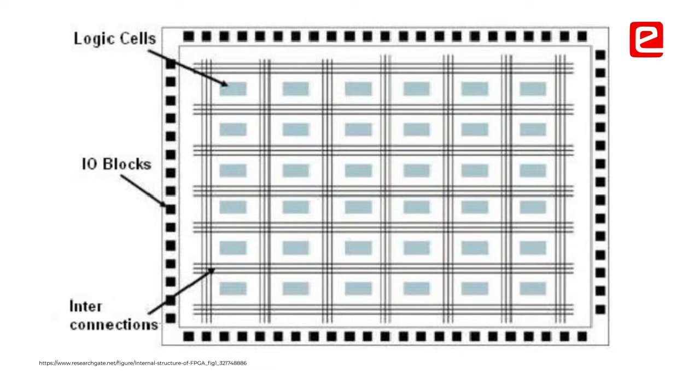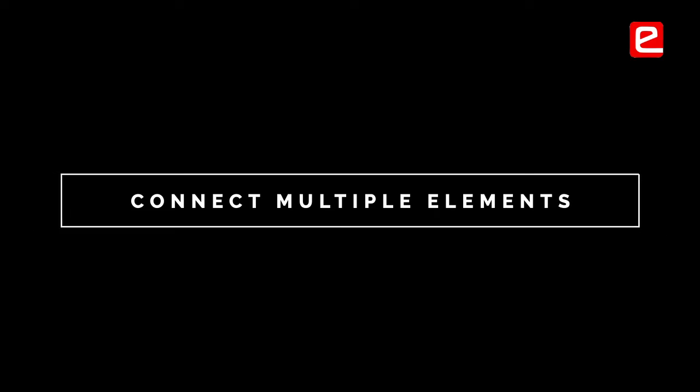The internal structure of FPGA consists, at the most root level, of just a bunch of mux and D flip-flops and some other logic elements inside it. So when we try to use a for loop like we were using previously, and 2D arrays, it doesn't know how to actually synthesize a for loop, because a for loop for a specific number of iterations would need it to connect multiple elements in a daisy chain or some other way, which was very difficult for it.